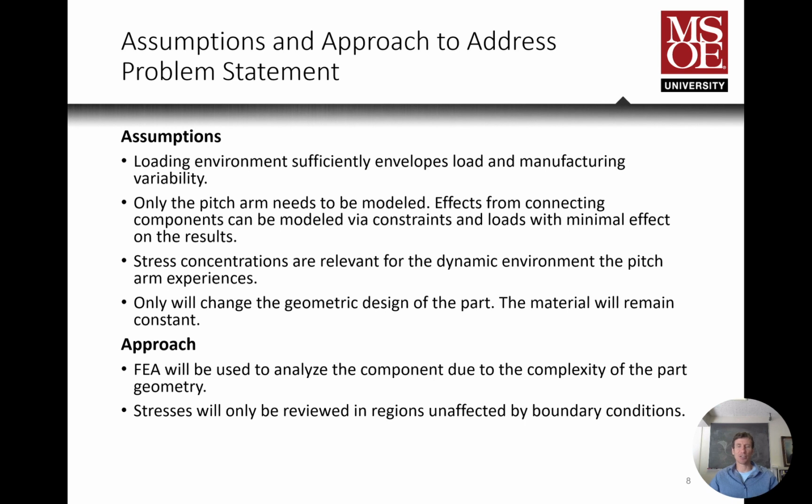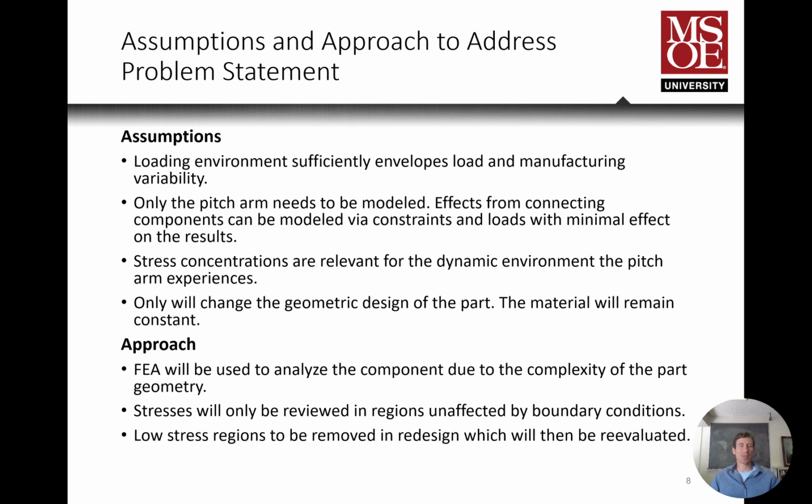So we're only going to look at the regions that are unaffected by the boundary conditions. And when we take a look at the low stress regions, we'll consider those for removal because those will have minimal impact on the load path for the part. Okay, and this process takes care of the pre-analysis step of the total analysis process, the total FEA workflow.